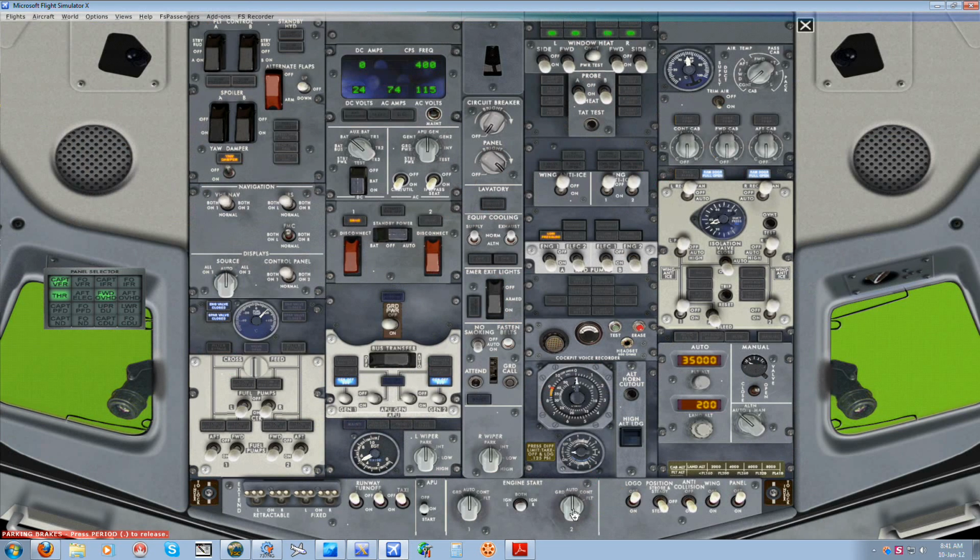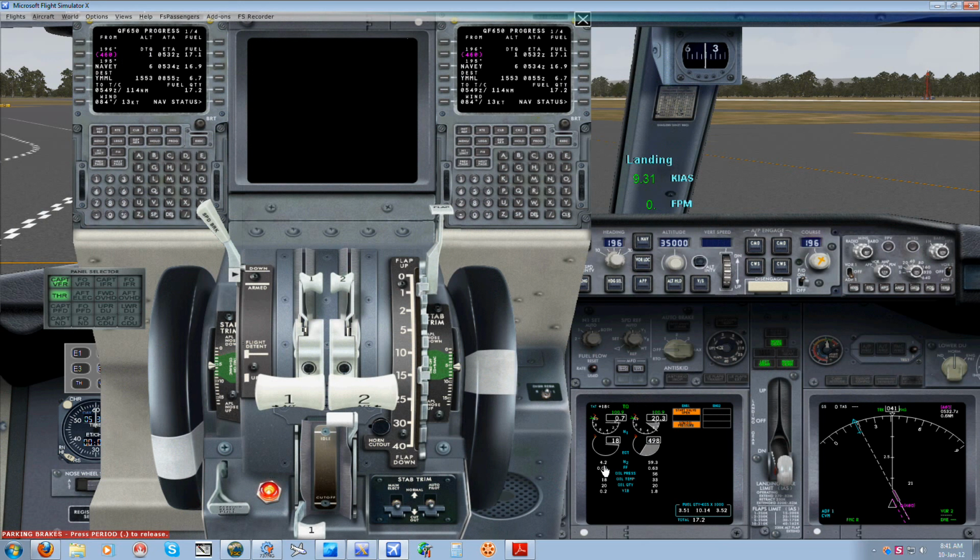That will automatically go back to auto. Once that actually hits auto, you can then do the left engine start switch to ground, close the overhead, and again we're looking for these numbers here. See these numbers here, they're coming up. So once that actually gets to 20.0, we can open up the fuel control valve for engine 1. So there's 20%, and we open up the fuel control valve.